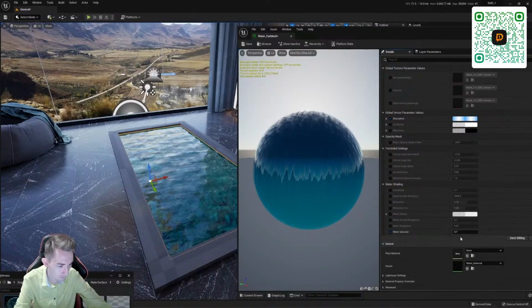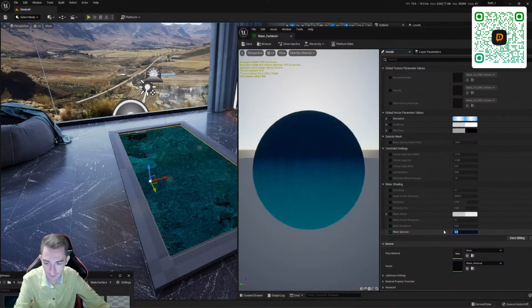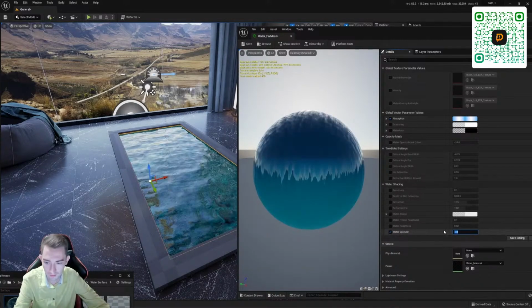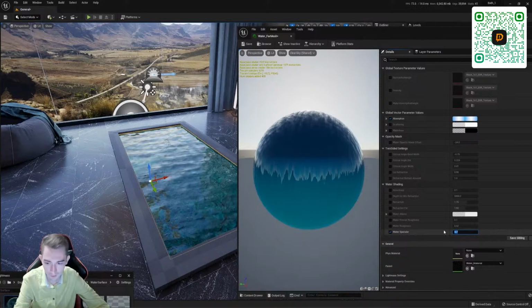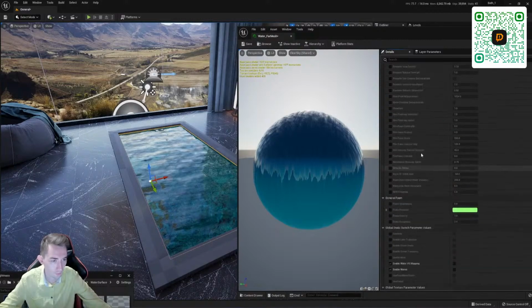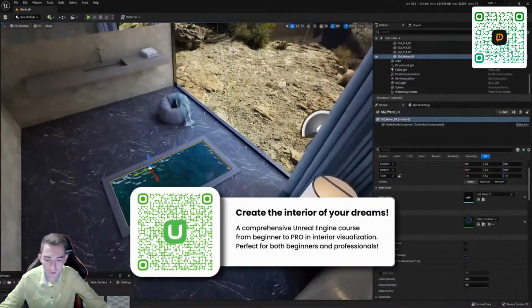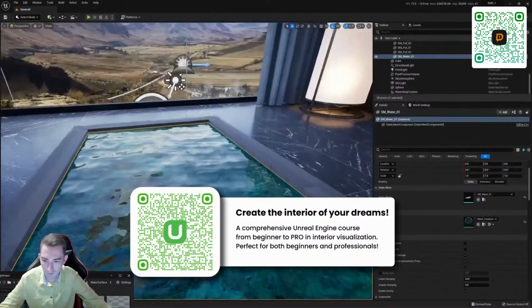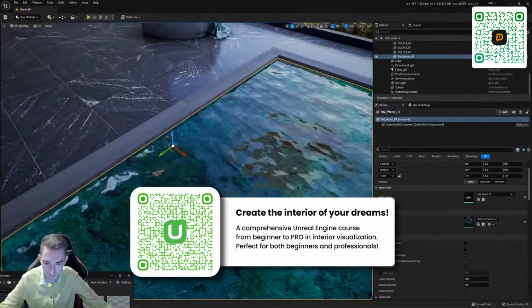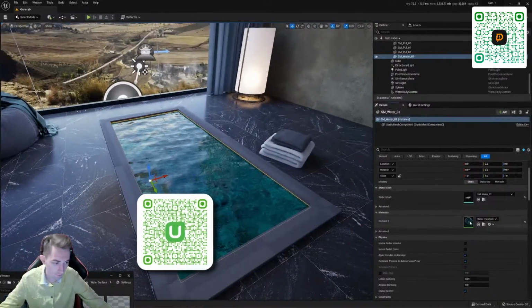This is the specular. This is our reflection. The interesting thing is that I set the parameter to 0.7. If I put 0, there are no reflections at all. 0.1, 0.2 and up to 1, we set some kind of reflection. Let's see how we like it more. This is how, in principle, materials are created simply. So, I set the scale too small.